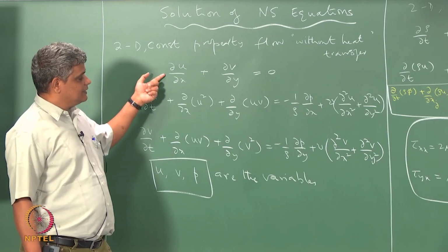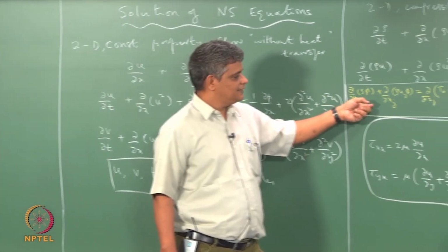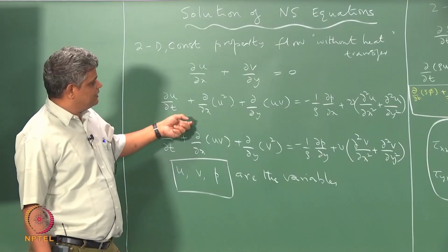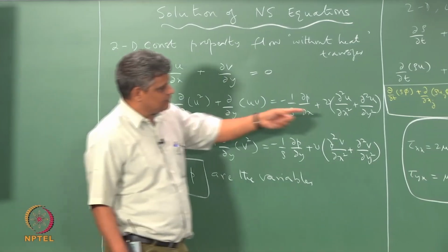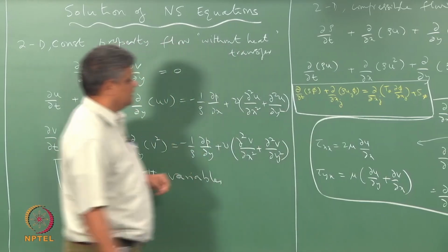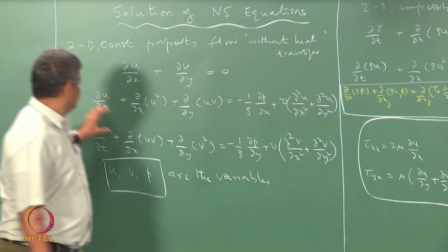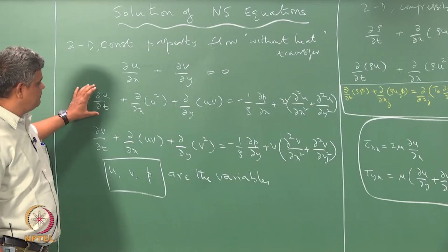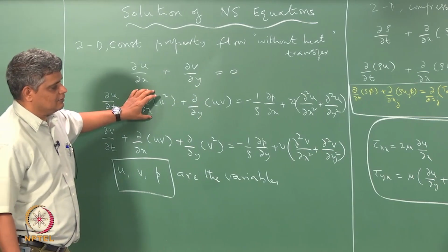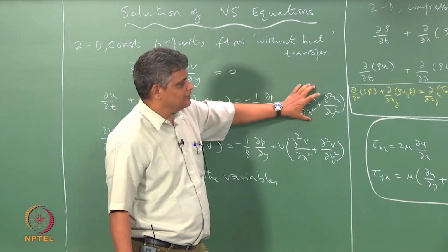Okay. So, in that sense it is not quite like the model equation. When you look at this equation here, it looks like you have similar kinds of terms: ∂/∂t term, convection, advection term and diffusion terms, and you can consider this to be like the model equation with a time dependent term, and the two terms arising out of the advection term, a source term which is the pressure gradient and the diffusion term.